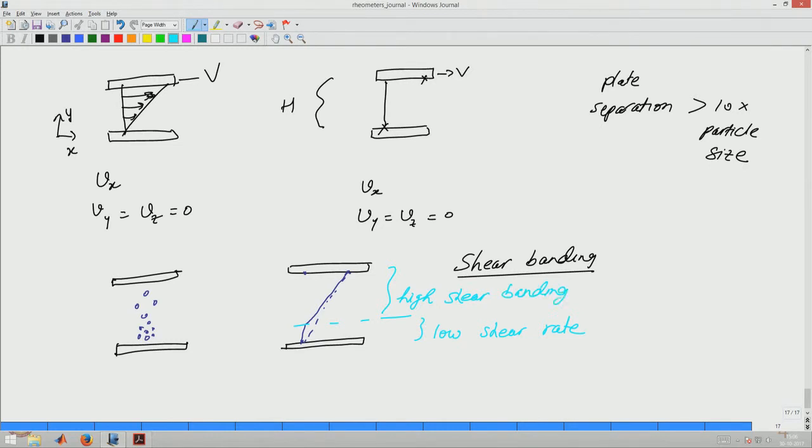One question that always could be asked is, should we be measuring rheology of such materials when there is settling, because in the end we would like to measure the properties of the material themselves, and if there is settling involved, then clearly we are not characterizing the material, but the settling phenomena.